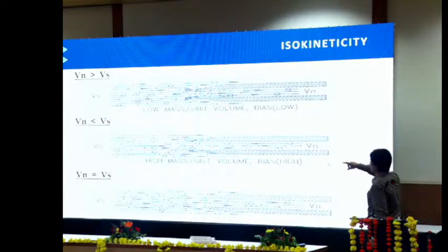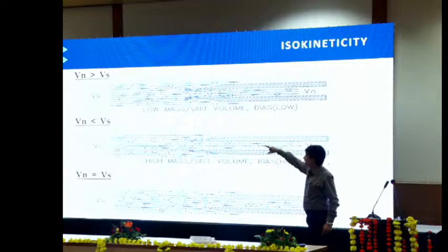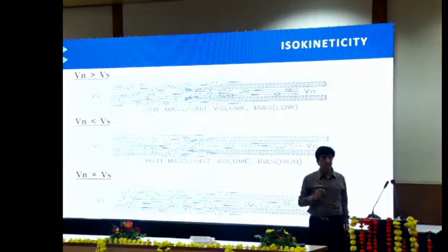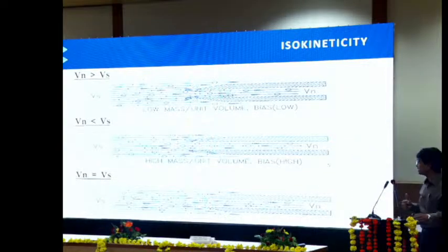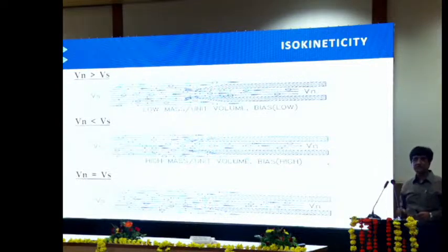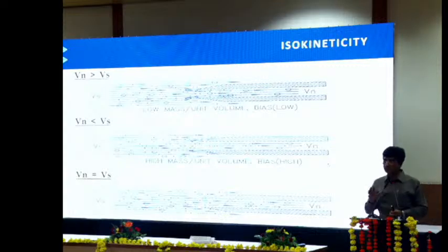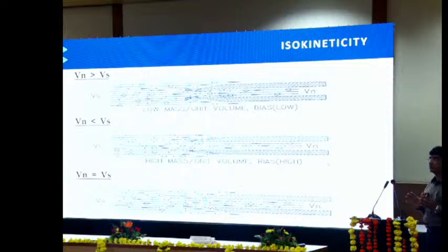But suppose the suction rate is higher or lower, then you will not be able to get the right concentration. So you have to be very careful that whenever we are doing the monitoring or sampling, isokinetic conditions have to be maintained. Do we need these isokinetic conditions for gaseous sampling also, for gaseous CEMS? No. Right. So this is basically an exercise we are doing for PM, particulate matter.